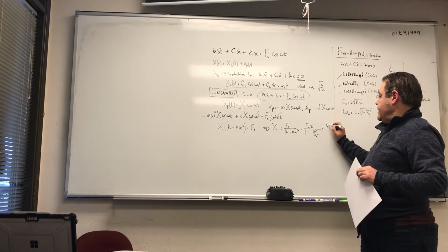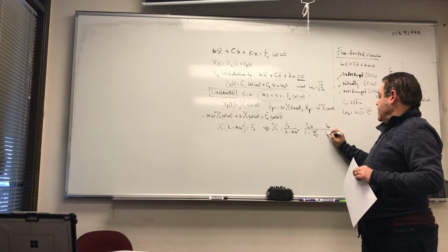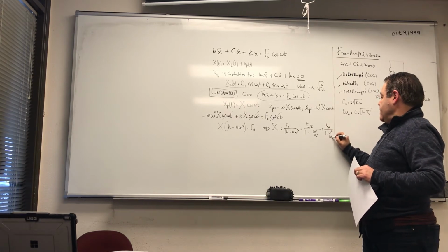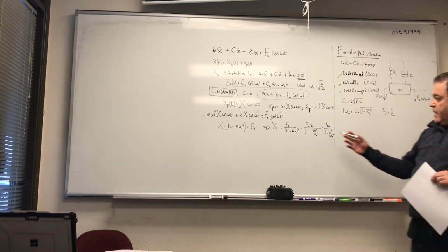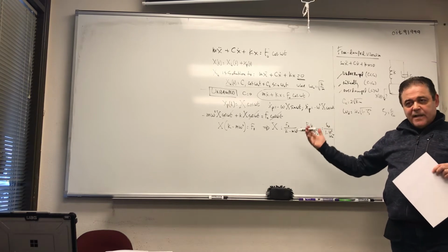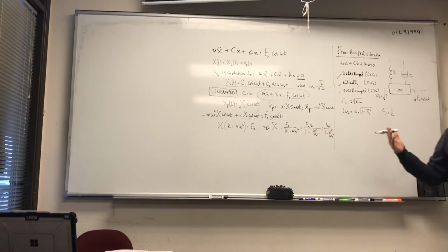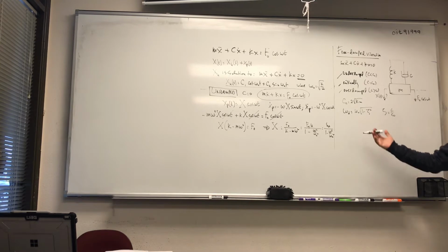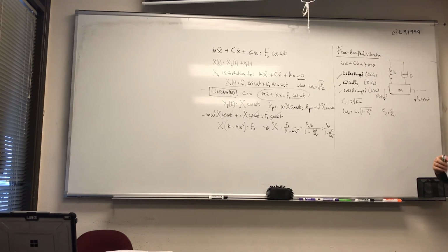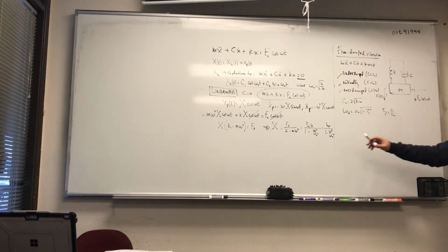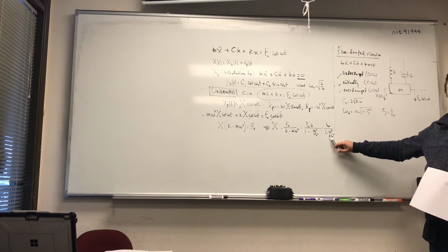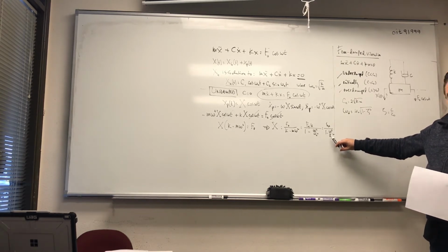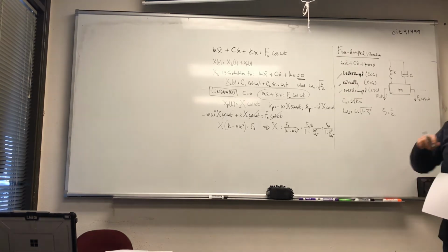And this is nothing more than delta static, right? 1 minus omega squared over omega n squared. So isn't this cool? You can find the amplitude immediately if you are given a problem like this and try to figure out the situation. Now, you can find it if obviously omega is not equal to omega n, because if that's equal, you're in trouble. Okay, let's do that.